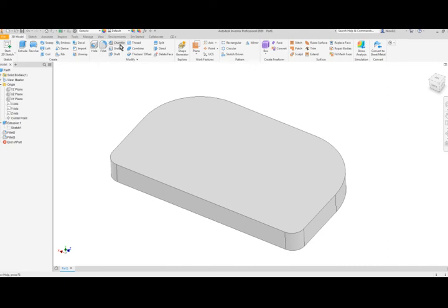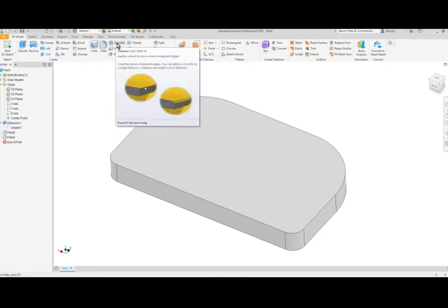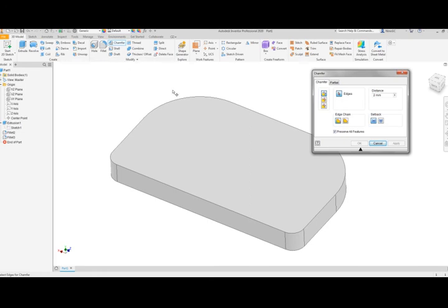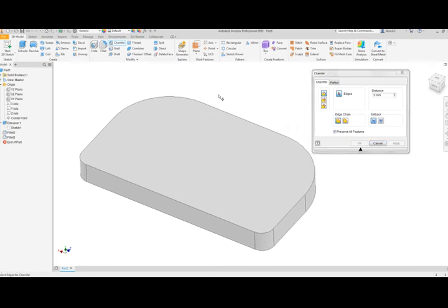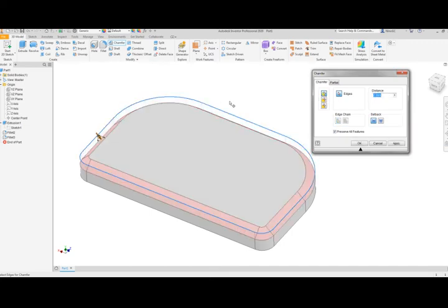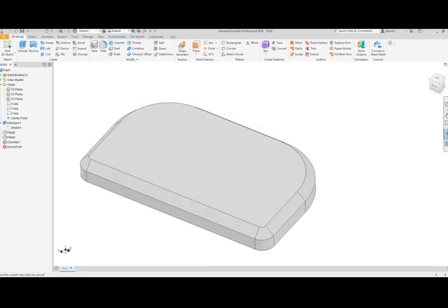And then I'm also going to demonstrate the chamfer. Chamfer is similar to fillet. The only difference is that the chamfer provides a straight cut edge. We have 3 styles of chamfers. We have distance, where each distance is equal, which means it is a 45 or a normal chamfer. We have the ability to indicate a distance as well as an angle, and we're also able to indicate 2 distances. We'll take a quick example of each. So distance, 45 degrees. If I select, it produces, in this case, a chamfer of 2mm all around.